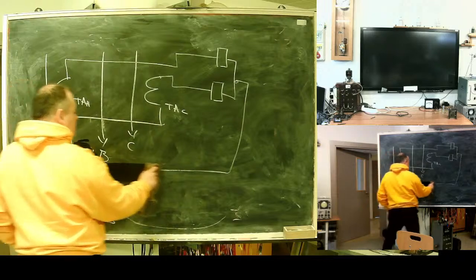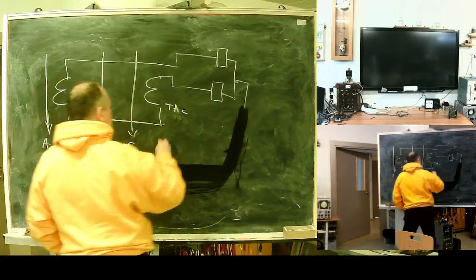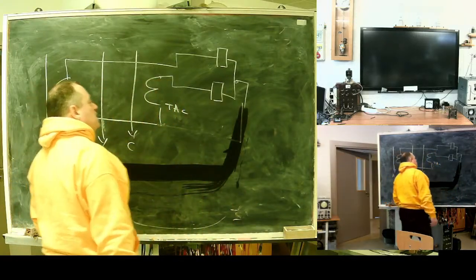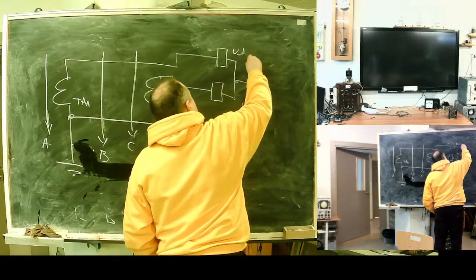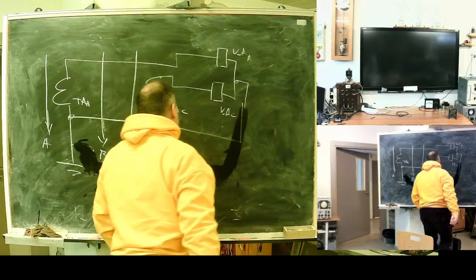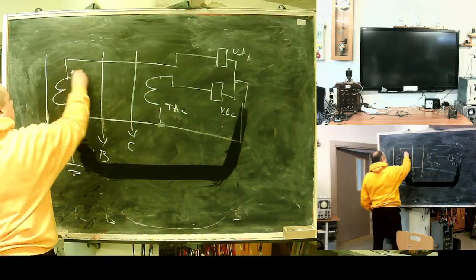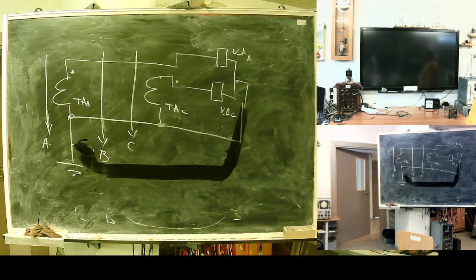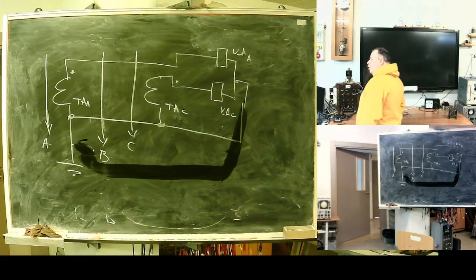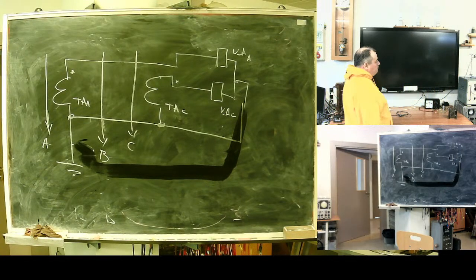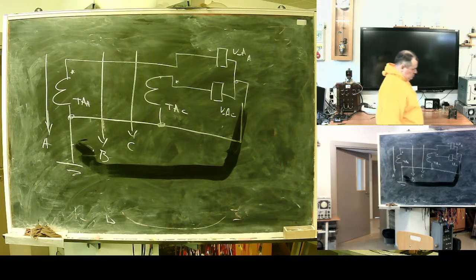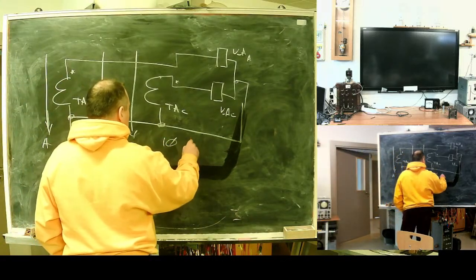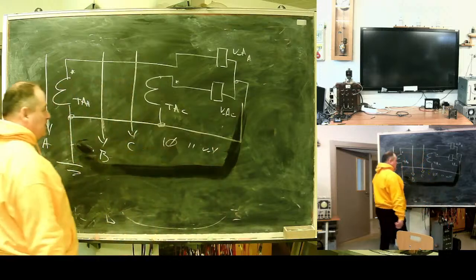It's not aesthetic. I need to draw aesthetic schematics. And relay for C phase. This one, incomplete star, or two relay star. This thing is popular for 10 or 11 kilovolt networks, for isolated neutral networks.